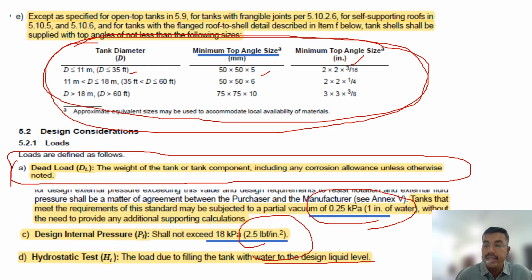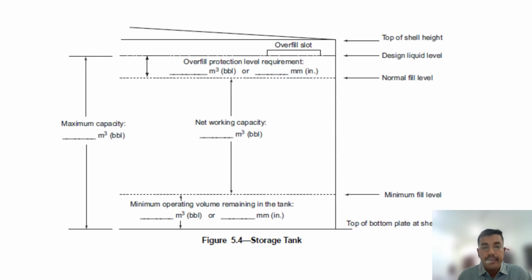They fill the tank, keep it for 24 hours, and that's it. It's called hydrostatic test. Here there are some basic terms I have mentioned: top of the shell height, design liquid level, normal fill level, minimum fill level, top to bottom plates. This is only for your knowledge, not for any questions in your exam.